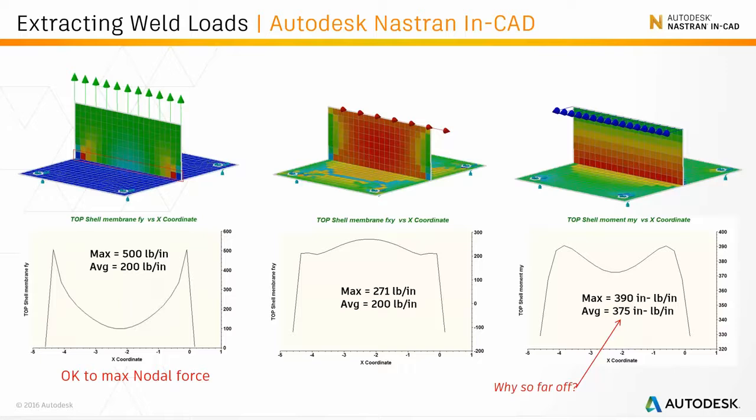You don't get the complete 2-inch length. So how do we solve this? Well, the easiest way would be to add mesh refinement along the edge of that shell element, and then reduce the mesh size down to a significantly small value so that the bending moment is accurately represented.